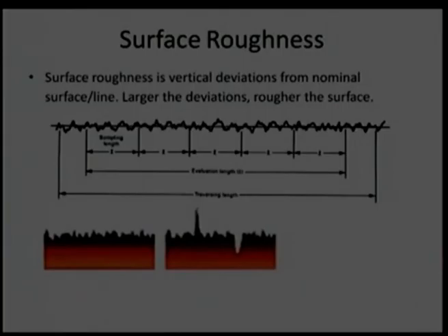Now, from the tribological point of view, as I earlier mentioned, we will be preferring a low surface roughness value compared to a high surface roughness. In other words, I will be preferring the left hand side image compared to the right hand side image. There is a possibility that the average surface roughness of these two comes to the same, because there is a value over here, there is a peak over here. If I sum up these two, I may get the same results, but I will be preferring this portion compared to this portion because of the lesser surface roughness on this side, or the lesser value of the peak.